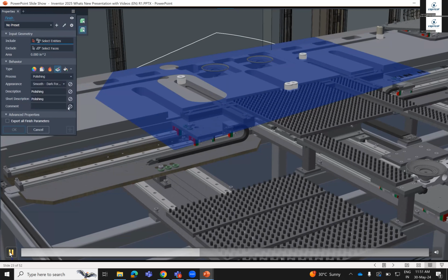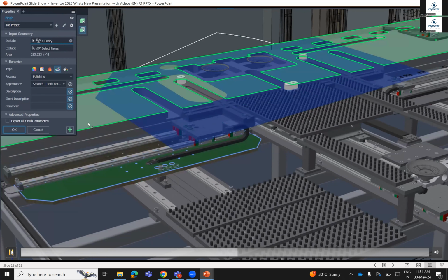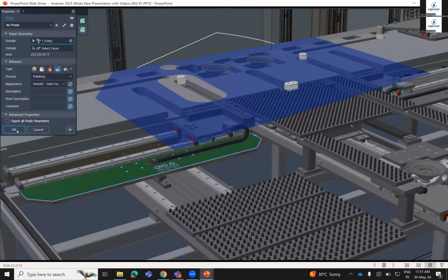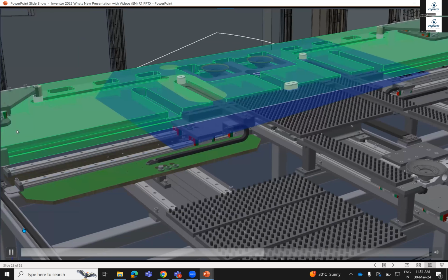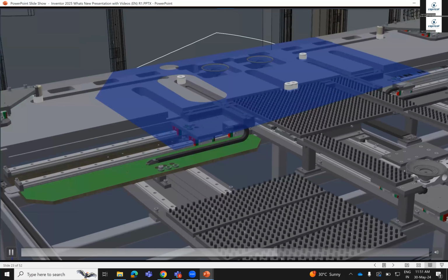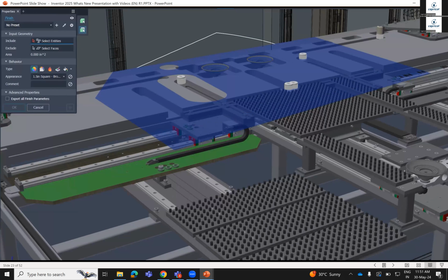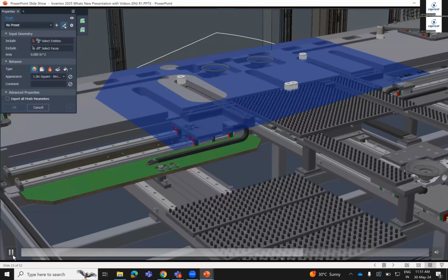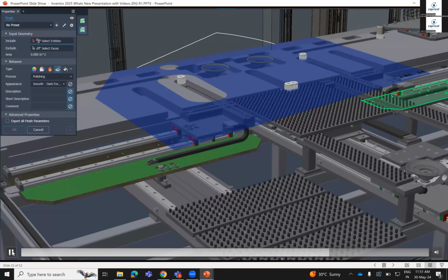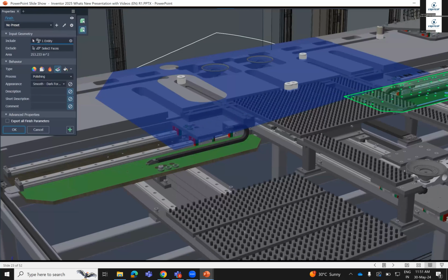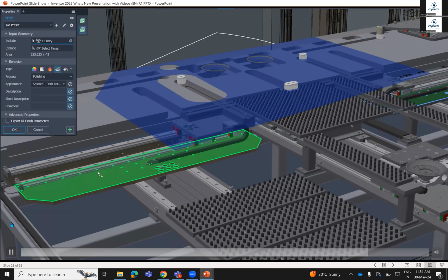Management consistency. Additional improvements include the introduction of selection filters and toggles for managing finish parameters. The addition of the eyedropper tool now streamlines the application of finish attributes, enabling a quick pick up and apply workflow. We also have new include and exclude buttons, along with body and face filters to aid in user selection. Support for including these selections in derive operations, such as make part and make component, has been added, along with the ability to disable parameter controls to prevent unwanted parameters.